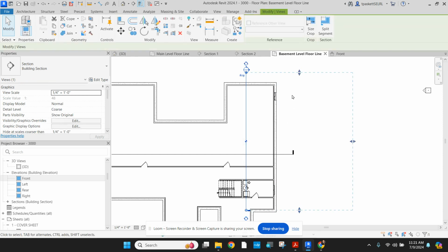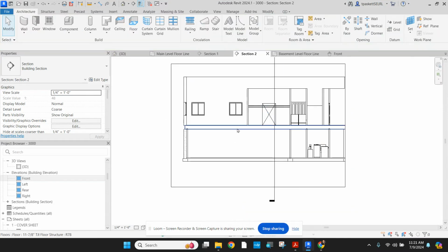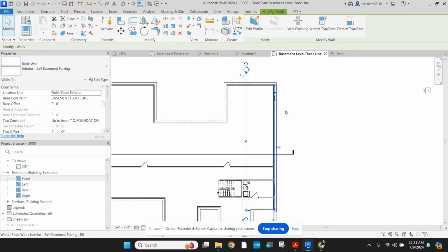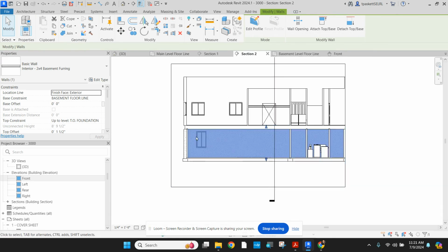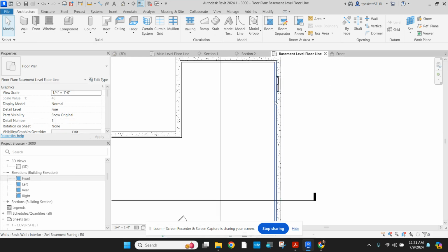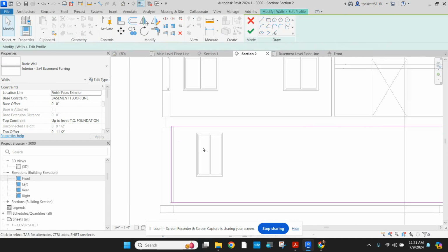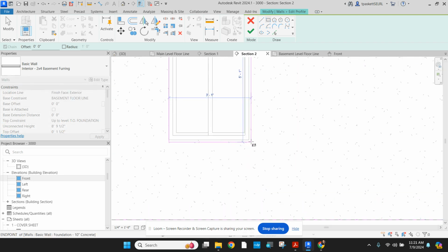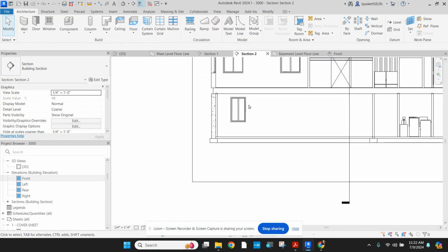It's in the view range. Go to the view. Go back and grab the wall again because it's being tricky. Actually, this wall's picking the wrong wall. I want this wall, the one in front. I picked the foundation wall. That one's fine. I need to pick the correct wall. There's my window. Oh, my goodness. So go back to it one more time. And now I can add that profile. And once I have the right wall, then I'm just going to take the rectangle and match the window. And this way, there's now a hole in the frame wall to the window, and so you can see it.